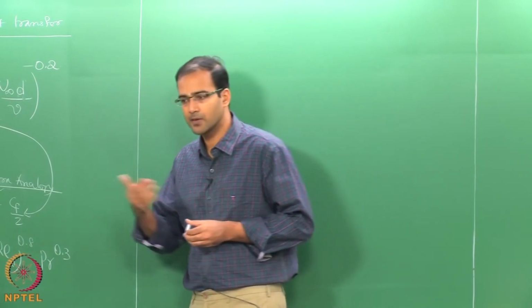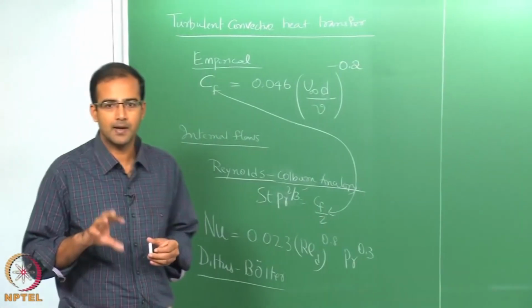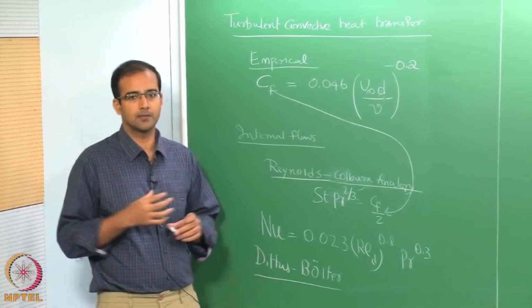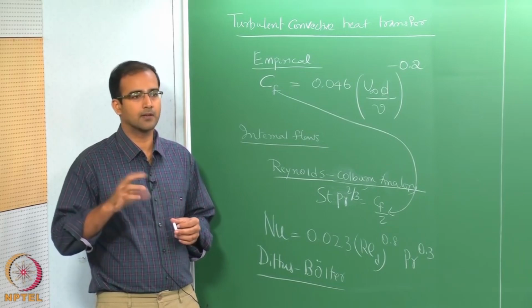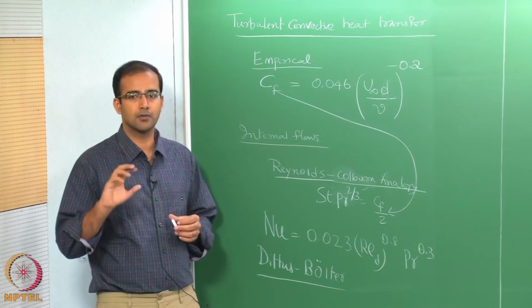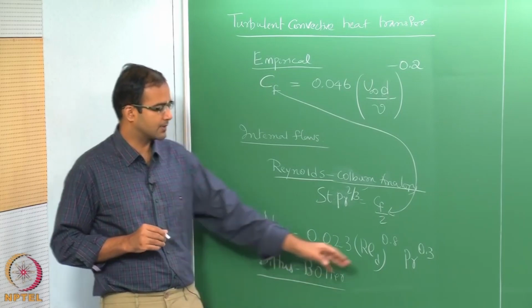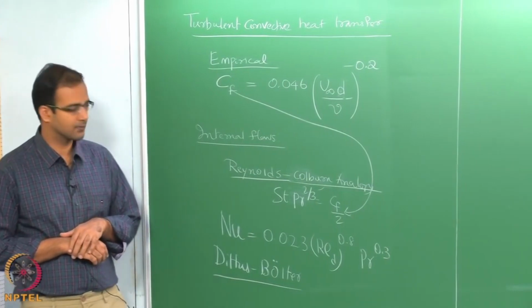Okay. So, then it has been slightly modified depending on the heating or cooling case, because the Prandtl number dependence is not a very exact dependence. It was introduced later on by Colburn, but it depends whether you have heating or cooling. There has been shown to be a slight difference, but not too much. Okay. Some people use an average value of 0.33 and they are still okay with that, right.